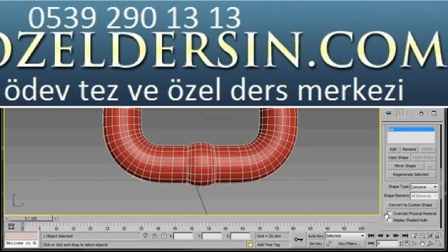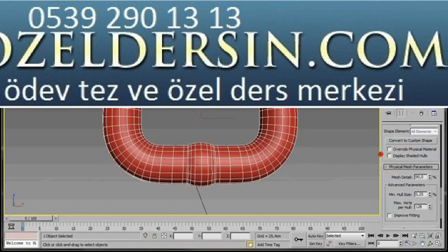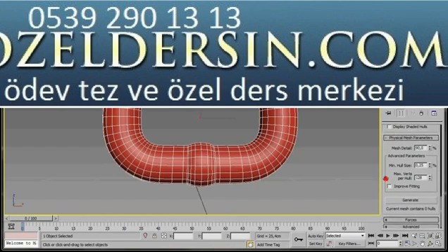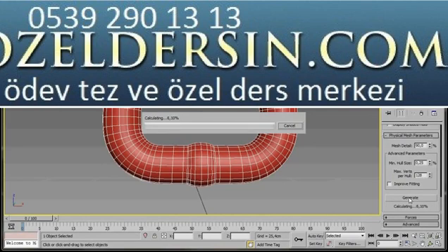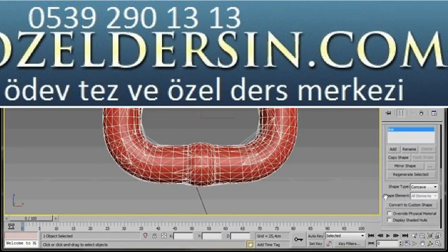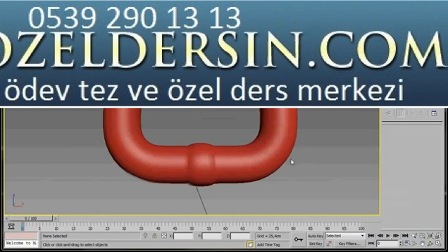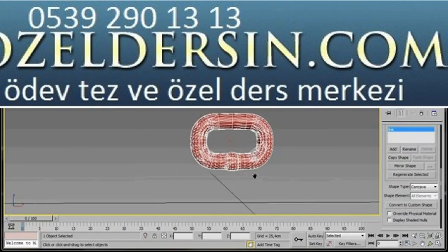Notice nothing's happened. In fact, the mesh has disappeared. So let's scroll down a bit further more to Physical Mesh Parameters, and here we'll find the Generate button. Let's click on it. Now it's calculating and it's creating its own mesh. We now can see we have a white mesh all around it. The default settings are fine for this video.